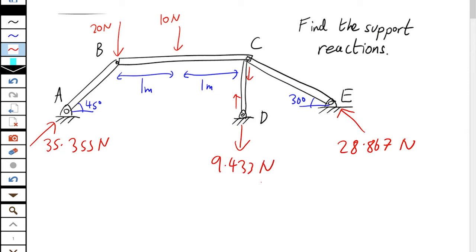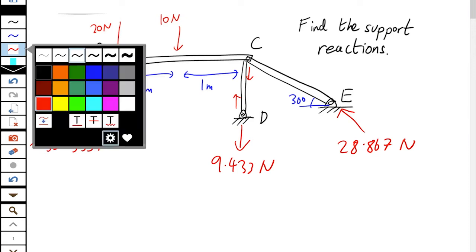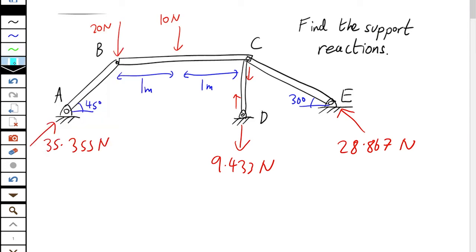which is fun. Also, a little bonus element I want to point out here. It's not part of this question, but I've seen it trip people up on past exams, so I want to make it clear. Something about this diagram here. Notice how they've drawn A, D, and E on their own little bits of ground. That means you can't assume they're level. I know A and D look like they're at the same level, but you cannot say that.